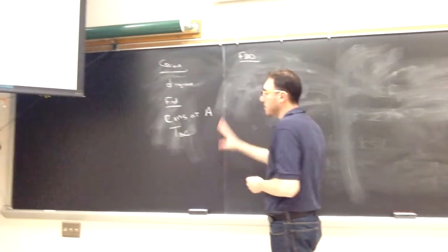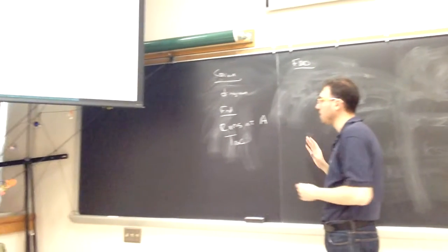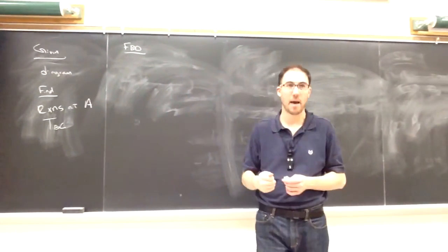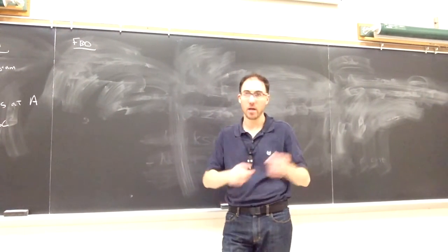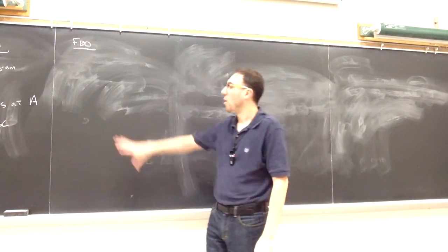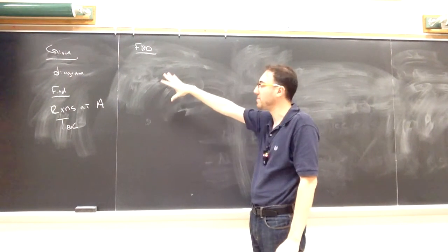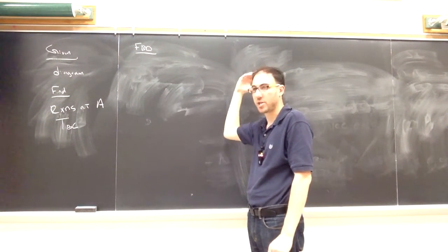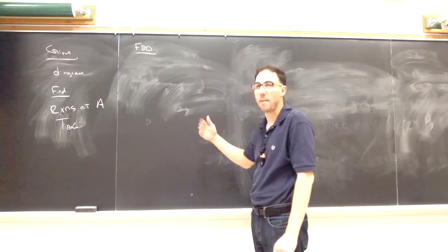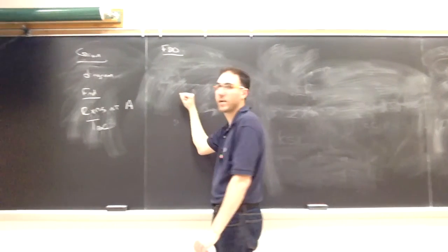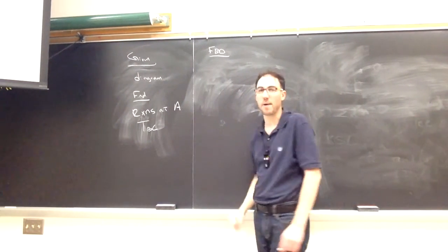When you go through a couple of these and get comfortable with it, the free body diagram step should be the difficult step. How are we modeling everything? What are all the orientations? Once your free body diagram is correct, the equations basically write themselves from the picture, and then it's just crunching numbers to solve those simultaneous equations. So this is really where you should be doing the most thinking, on the free body diagram.